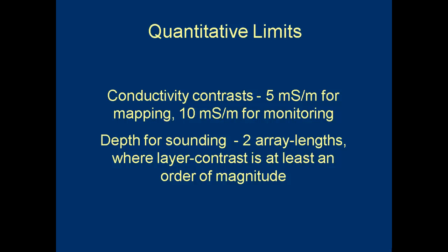The horizontal coplanar array has the greatest depth sensitivity of any array used in near-surface electromagnetic induction instruments. Its sensitivity function suggests that near-surface electromagnetic induction, as described herein, is limited to a depth equivalent of about 2 array lengths. The Loess over clay sounding example supports this guideline.